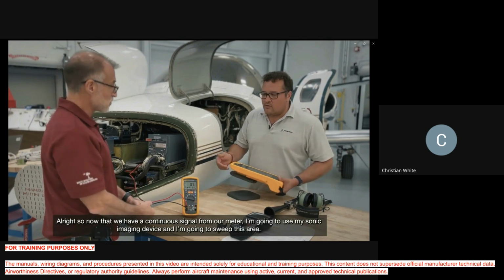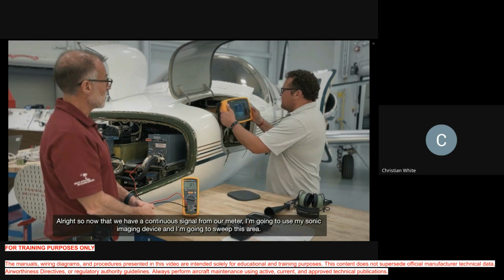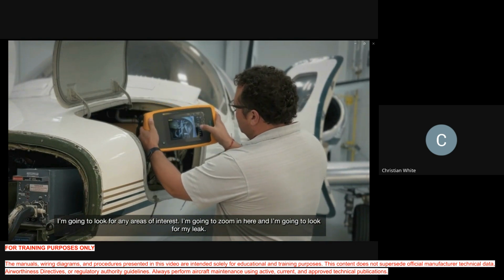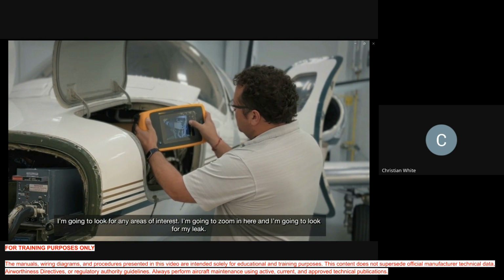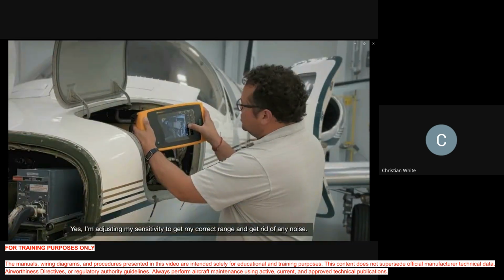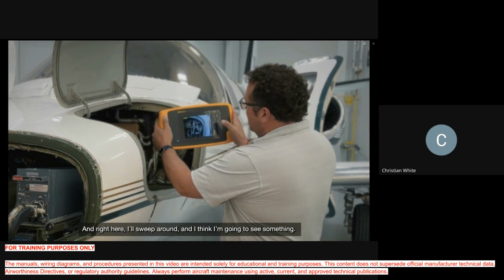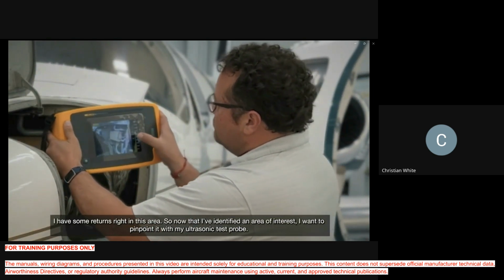All right. So now that we have a continuous signal from our meter, I'm going to use my sonic imaging device, and I'm going to sweep this area, and I'm going to look for any areas of interest. Now I'm going to zoom in here a little bit. I'm going to look for my leak. Oh, so he's moving his frequency range right there. Yes. I'm adjusting my sensitivity to get my correct range, get rid of any noise. And right here, I'll sweep around, and I think I'm going to see something. I have some returns right in this area.